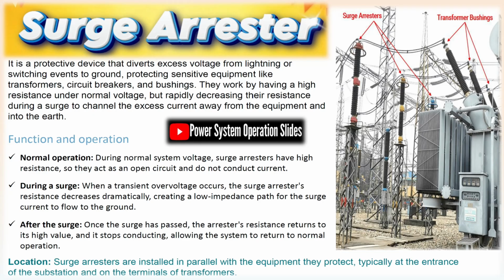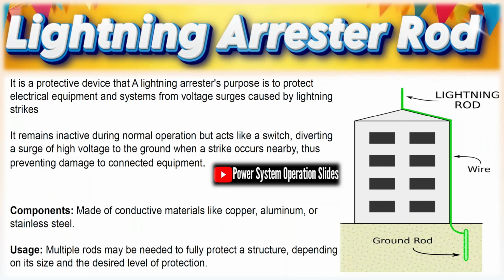Overcurrent relay types. Instantaneous, definite time, and inverse time relays provide graded overcurrent protection. Inverse curves vary from normal to extremely inverse. Coordination ensures proper fault discrimination.